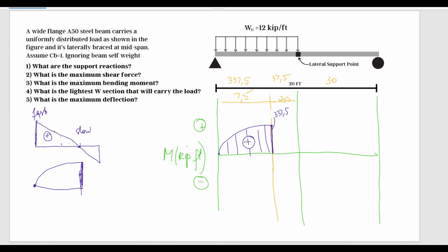Great. Now, next piece of the shear diagram looks like this. Okay? And if we do the ski slope analogy here as well, first we're going to talk about the fact that this shear diagram is negative, which means we're going to go downwards towards the negative side. That's one thing. Another thing, this shear diagram is linear, which means our moment diagram is going to look parabolic.